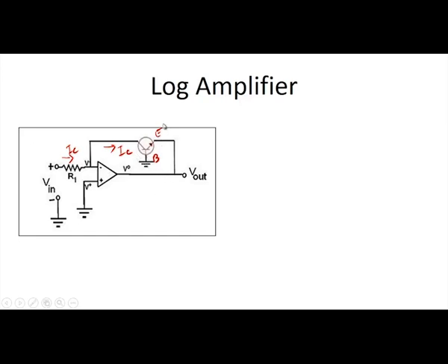And we can write the voltage equation for the emitter from the diode equation. First we can write the equation for IE. IE is equal to the saturation current IS into e power QVE by KT minus 1.